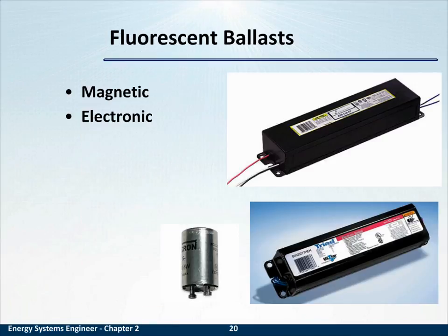There is a side of fluorescent lighting that we haven't discussed here as we walk through different types of fluorescent lighting, and that is the requirement of a ballast. Think of a ballast on a ship. A ballast on a ship is meant to keep it at a certain depth. A ballast on a fluorescent lamp is meant to keep the current at a certain level. And why is that necessary? Well, in most materials, conductivity at a given temperature is constant.